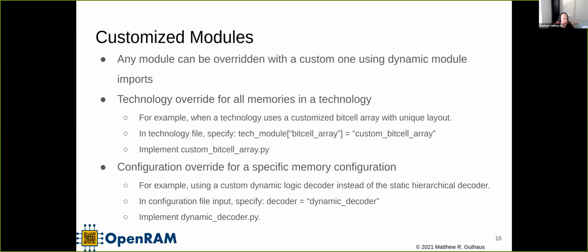In the first tape out, they did kind of a hack where they took OpenRAM and added stripes on the side and connected the power to the stripes on the side by hand, because they didn't tell me that it wasn't working with the tools nicely. So I didn't know I had to patch it. But does that answer your question? Yeah, it does. But I'm also not sure why you're using power routing. Why not just stitch everything together with the power as well?